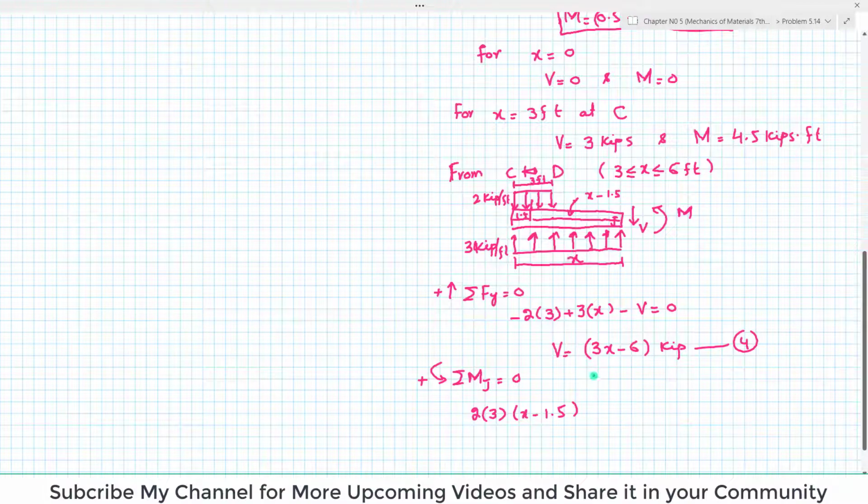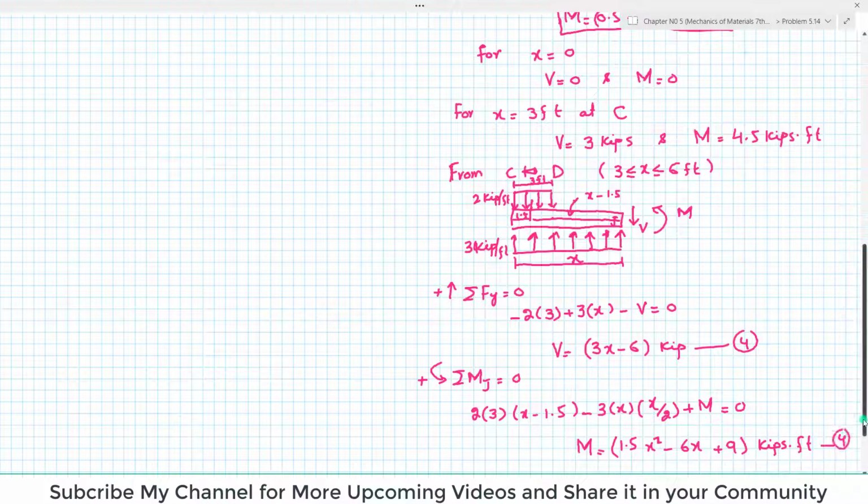The other force which is producing moment is this 3 into x, and it will be acting at a distance of x by 2, because it will be acting at the mid of x, and this is producing clockwise moment, so it will be negative, plus this external moment, their sum must be equal to 0. So from this you will get the equation of moment M equal to 1.5x square minus 6x plus 9. This is the equation of moment, and the unit will be kips into feet. And this is your equation number 4.